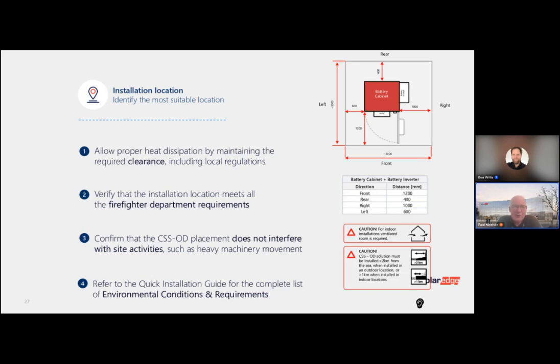So you'll want to follow these always, in fact, not just whenever possible, but always. Also monitor the location of the systems. Again, it can't be too close to very saline conditions, so close to the coast, or even to very humid conditions, so close to large banks of water. So, again, do discuss with us, and we can have a look and see what the localized conditions are so we can advise whether it is or is not appropriate for the installation of the CSS-OD in that location.